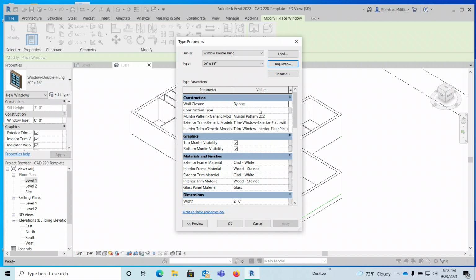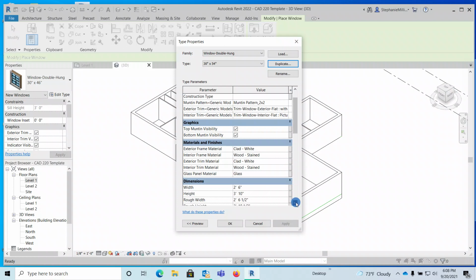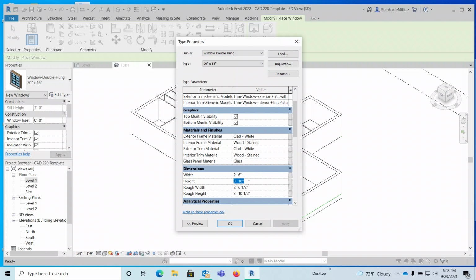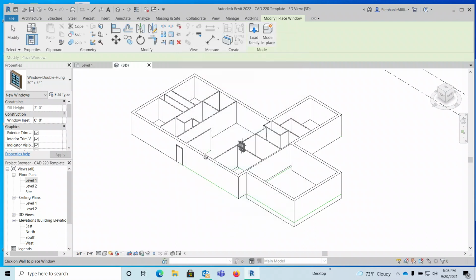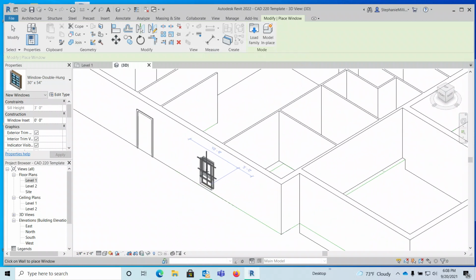It's not as hard. So everything else kind of stays, but I need to come down here and change the height. So I picked 54 inches, so that's roughly 54 divided by 12. Oops, sorry. Is 4'6". So we're going to go in here, change that to 4, 6, and then we're going to have to update. So clicking in the box, updated it, added the rough openings, say OK, and now the symbol gets updated to match the height that I wanted.